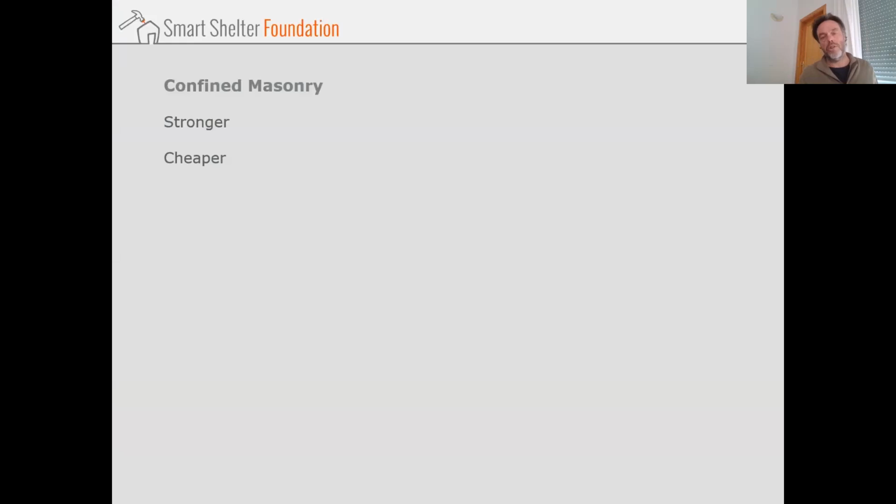But confined masonry, I just wanted to show this in just a few minutes, that this would be my suggestion always for, let's say, 4 to 6 stories high. Go with confined masonry rather than with concrete frames, because it's proven. We know that since the 1930s, Chile and many South American countries built with this. And unfortunately, in Turkey, this was only introduced in 2018, with the latest seismic code. And hopefully more people start building with this, rebuilding with this now.